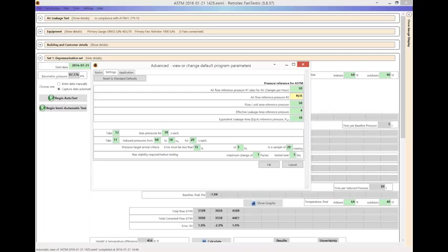And the final point there is that if you're running your fans at maximum speed, if you get them all overheated at low speed and then try to run them at high speed for your final point, you might have a good chance of blowing the breaker. Obviously, with small fans, it's not a problem, but often when you're doing a multi-fan test, particularly in the US at 120 volts, there is a good chance you're going to pop the breaker. So you want to get that point established first. Once you achieve your highest test pressure, there is less heating involved on the breaker and much less chance that you're going to pop it mid-test and destroy your test.